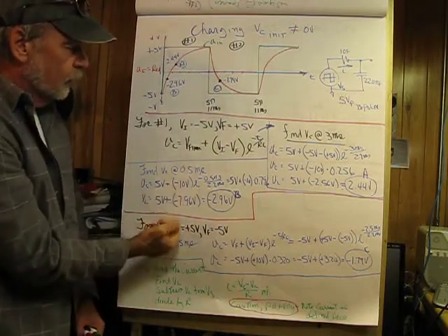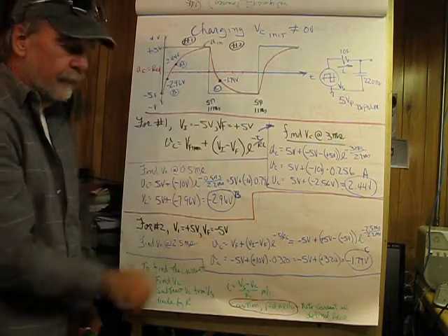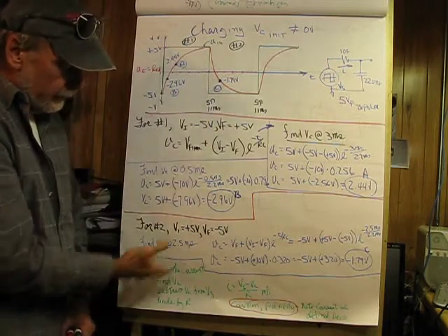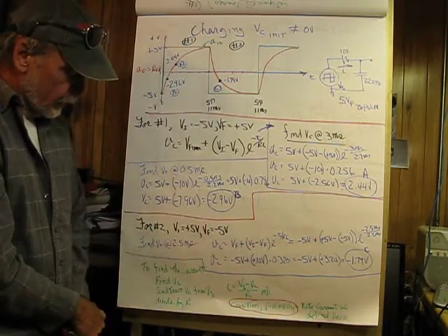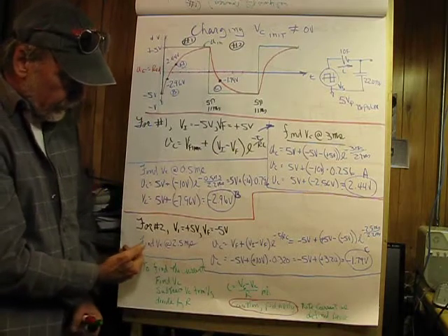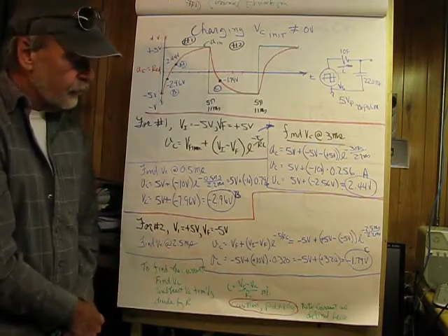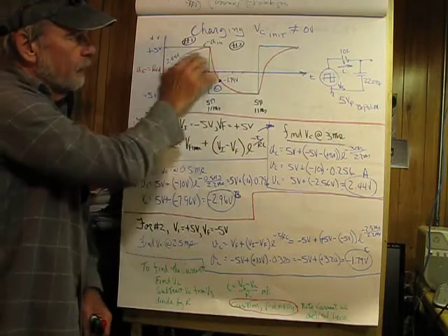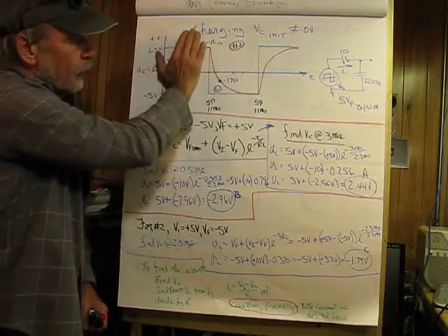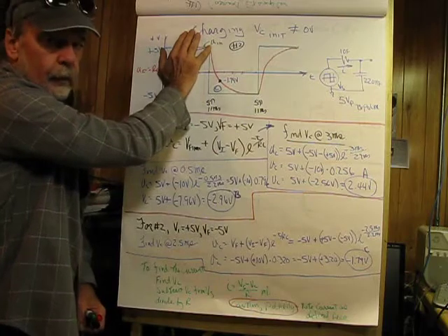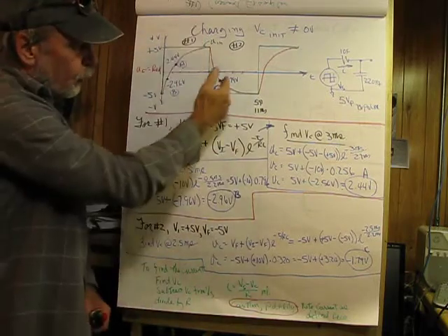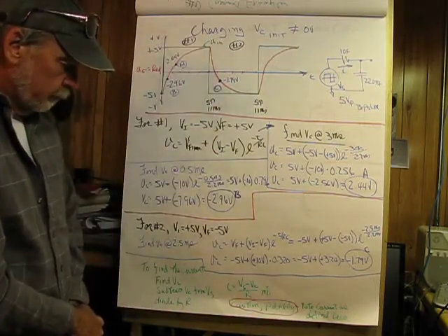And our final voltage is going to be negative 5 volts. So we can't switch around these values in the equations, and what we desire is to find the capacitor voltage at 2.5 milliseconds, and that is relative to number 2. So this is going to be our starting point right here, and we want to go 2.5 milliseconds into that.